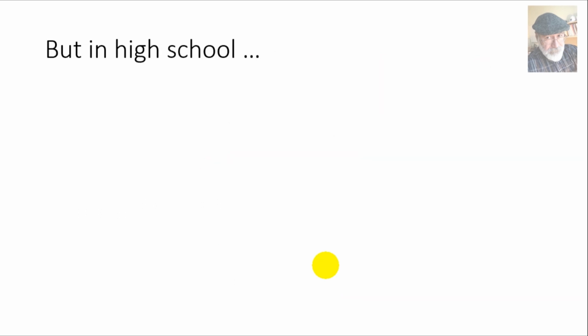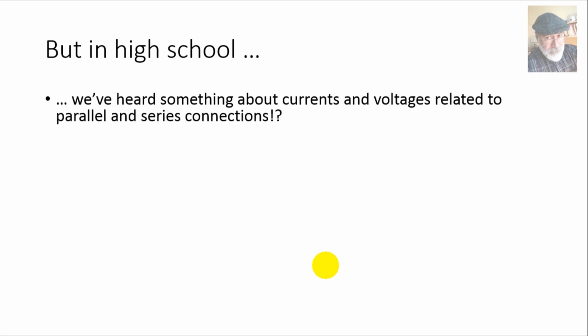Let me dispel a misconception that we've been carrying around, perhaps from our days in high school. Not that the prof taught us that way, but we somehow concocted the idea that if two elements have the same current, they are in series. Wrong. But if two elements have the same voltage, they are in parallel. Wrong. Those are consequences. It is true that if two elements are in series, they carry the same current. It is true that if two elements are in parallel, they have the same voltage. But it works only in one direction, not in the opposite direction, as we shall see.